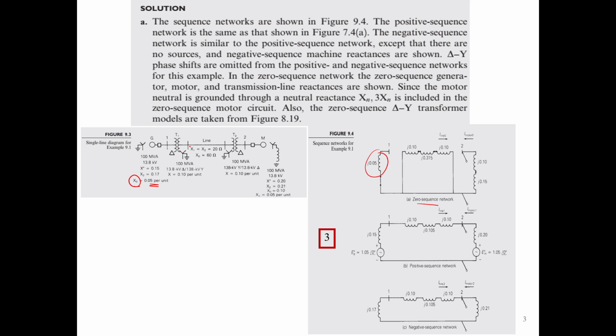In this case it is delta. The X of this transformer, we normally assume, is on the primary side, and it is delta connected, so it creates a loop. Since the secondary side is solidly grounded, it is connected to the ground.